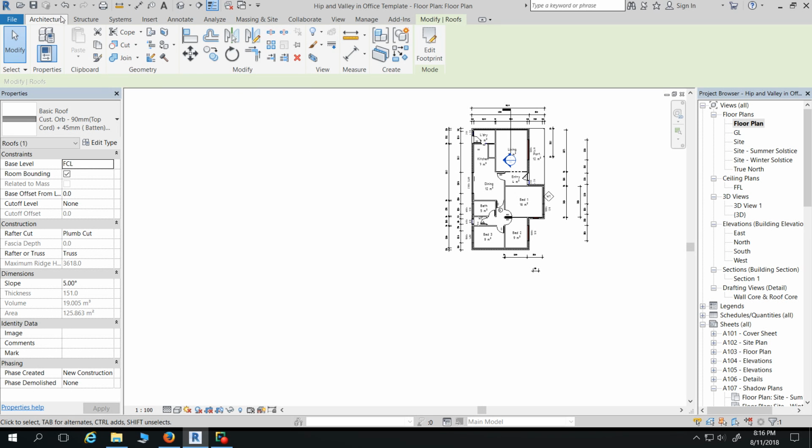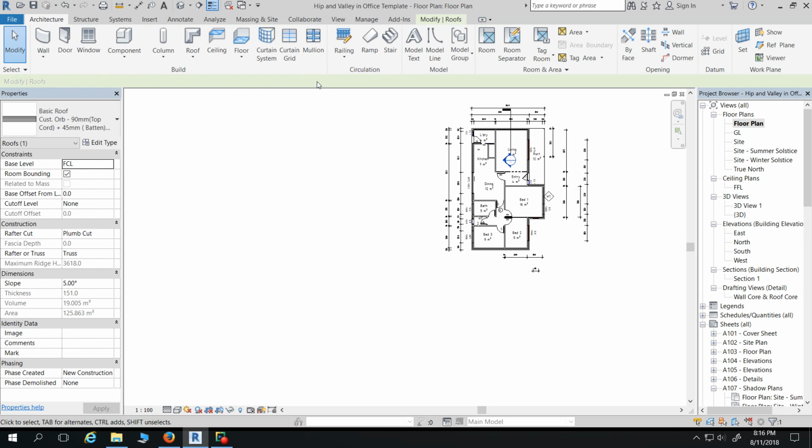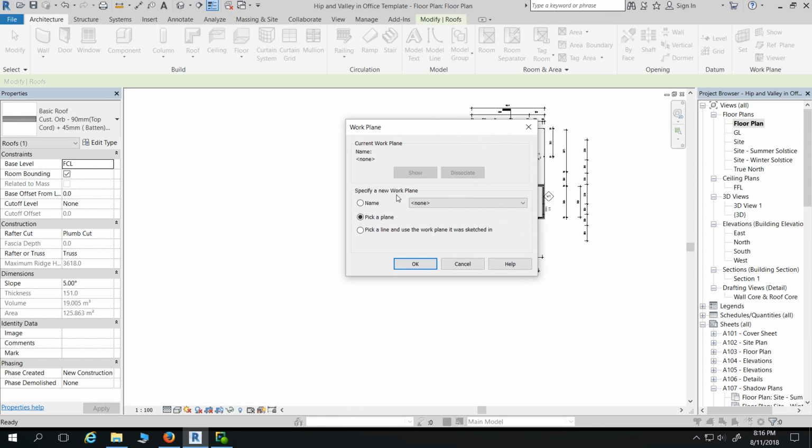So the roof by extrusion is pretty simple. So as that as it sounds. The roof sitting on the brick out course, that truss, is that how it should be? Or not? It may just be how that generic roof is set up. Right. So, because for mine it worked where it's got the core. Yeah. So if you just check the structure of that roof, it probably does have the core, but